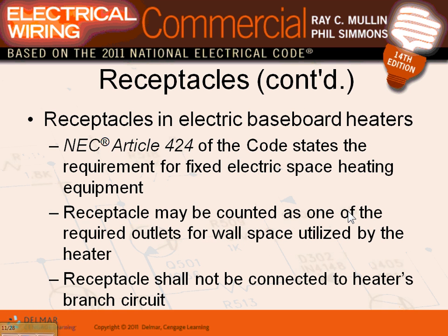If you have receptacles in an electric baseboard heater, that's also considered receptacles. I wouldn't see this used in a commercial building. This is mostly residential probably, but you could have a baseboard heater in one area and you need a receptacle too. Two birds with one stone. You put the baseboard heater, bring a 20 amp circuit to feed the baseboard heater, and another 20 amp circuit to feed that receptacle, which is part of the baseboard heater. So you can't feed the baseboard heater and the receptacle from the same circuit.